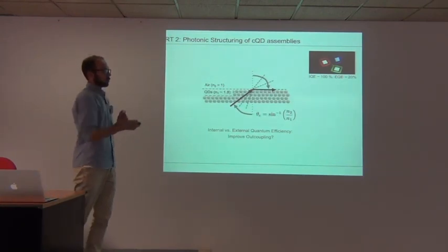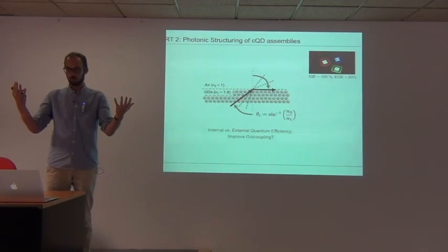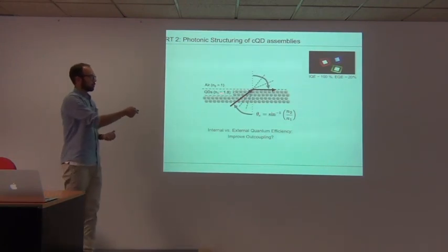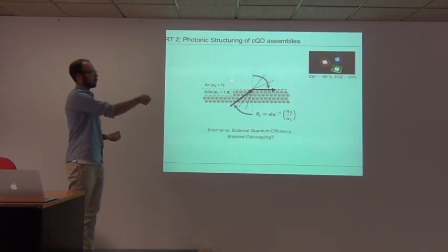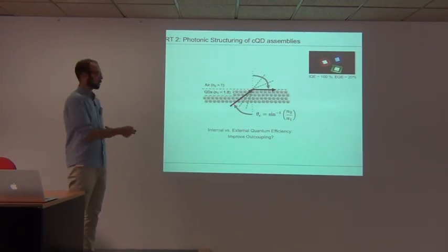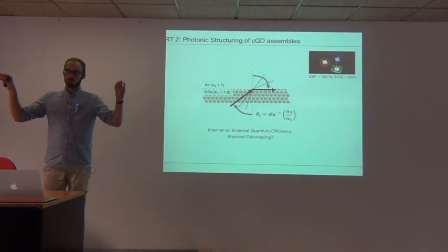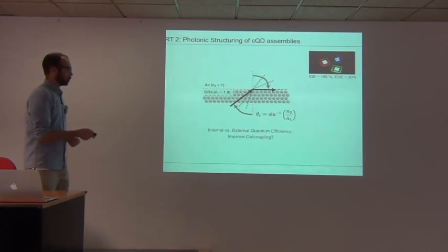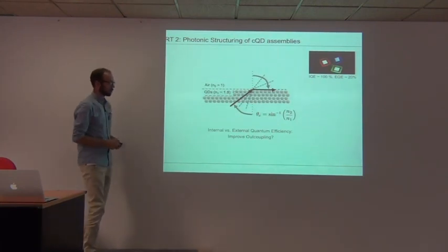That means that basically for every electron that you're injecting, you get a photon generated. But the external quantum efficiencies are quite low. What does that mean? You are very efficient at generating light inside your device, but getting it out is a different question. Typically, you generate this light inside a film which has a relatively high refractive index of around 1.8, and only light that goes out in certain perpendicular directions is able to escape, but a lot of the light is actually trapped in waveguide modes. So when you look at one of these LEDs without any light management system, the edges are extremely bright, because the trapping efficiency is on the order of 80%, which explains this external quantum efficiency of only 20.